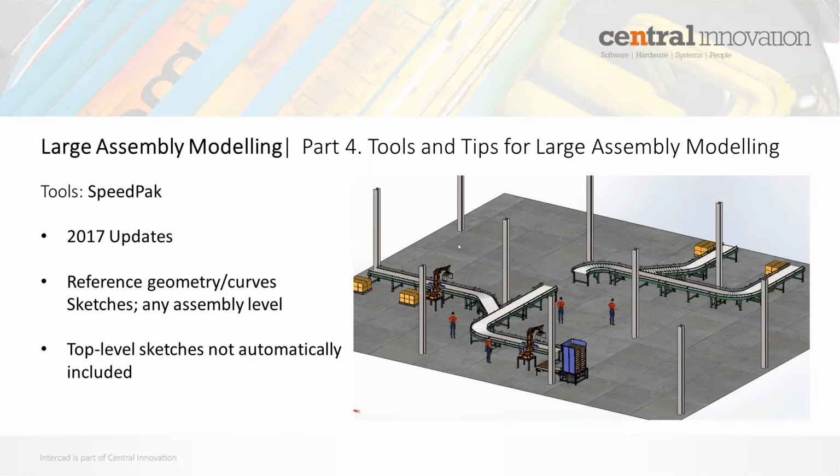So let's talk a little bit more in depth about SpeedPAK. SpeedPAK's had a bit of a bumpy history in terms of use and stability. This has been improved in the last couple of releases. For 2017 specifically, some of the updates there are you can include reference geometry and curves in the SpeedPAK, and you can select sketches from any level of the assembly to include in a SpeedPAK.